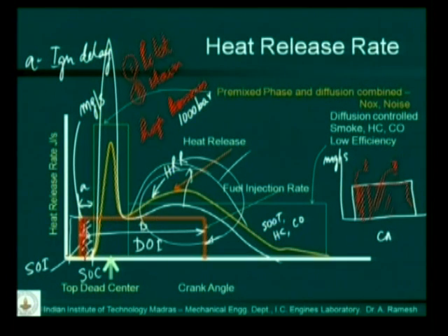Even a small leak can be really disastrous, because if something leaks, it can virtually cut. If there is a spray coming out and if we put our hand, it can actually cut through the hand. So it is a very complicated system. And why we use such high pressures is to actually boost the diffusion combustion phase. We want to raise this diffusion combustion phase, and for that we need high pressures. And we do not want to boost the pre-mix combustion phase, so use a pulse.